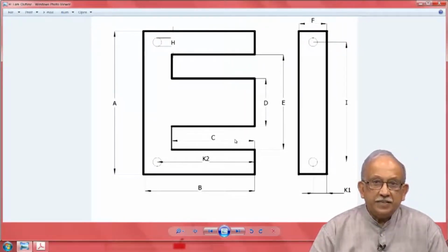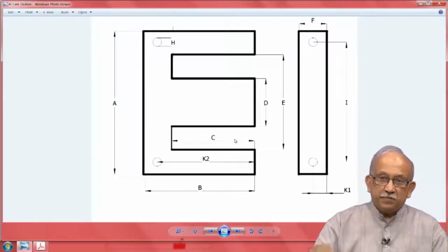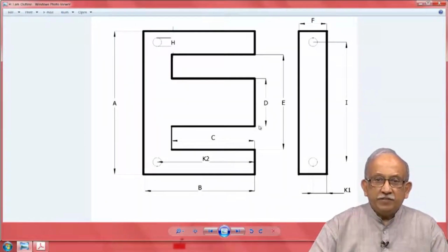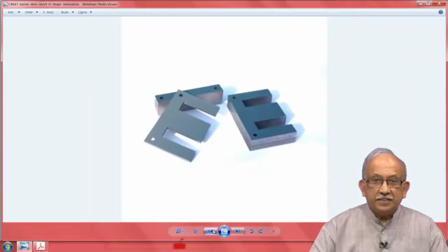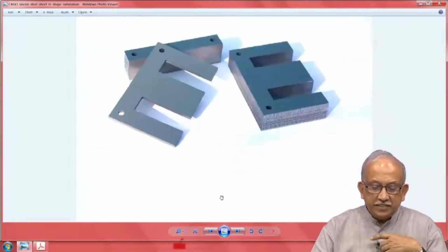This is how optimization is typically done in the tools which are used for this. In this case, it is probably made with a stamping die. So, you have a progressive blanking die where the strip is moved continuously and all the time the operations take place, and in the end you have a beautiful stack of nice laminations like this. I have a beautiful stack now, if you see here.